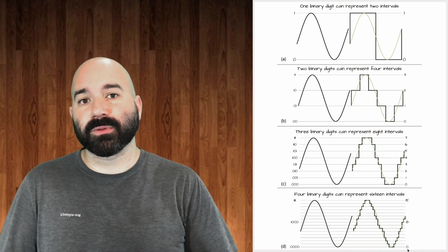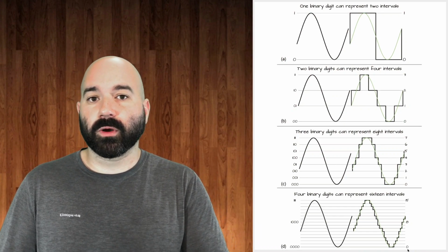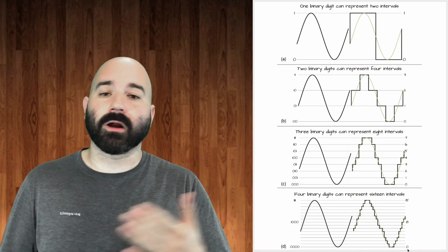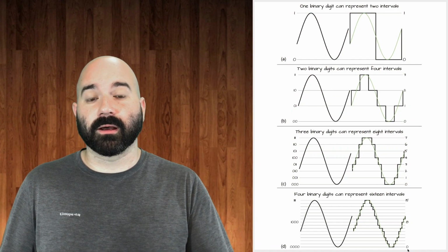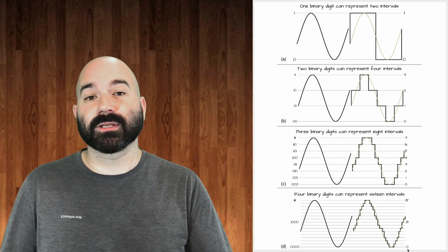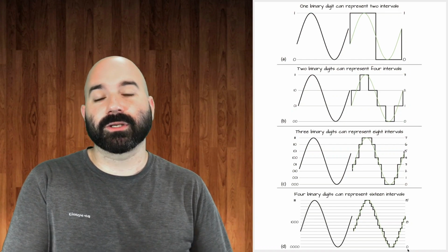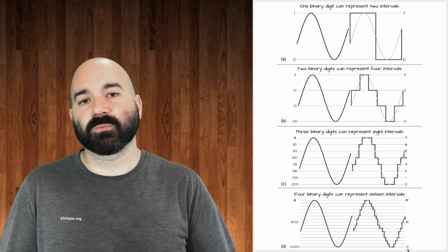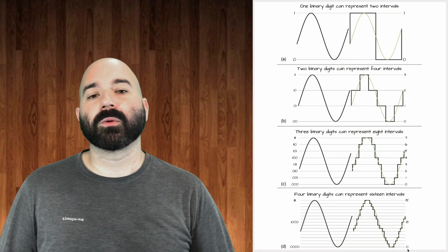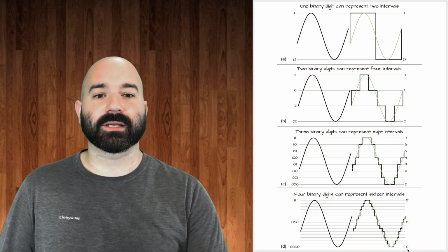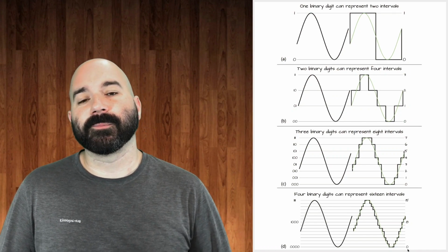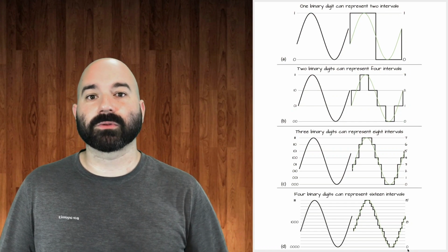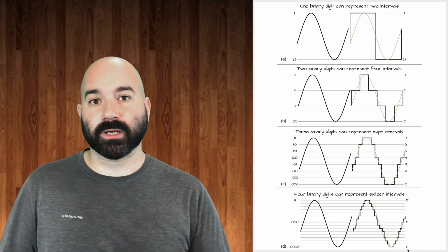Now, when it comes to sampling, 44.1 is enough, because if you're just recording something for human ears, our upper limit is 20 kilohertz. Recording at 44.1 kilohertz, you're going to get those high frequencies, but you might miss a little bit; it's perfectly fine. So if you want the best of the best, you get 32 bits at 96 kilohertz. But you're going to take up a lot of hard drive space, because remember, more bits, more samples equals more data equals more hard drive space.